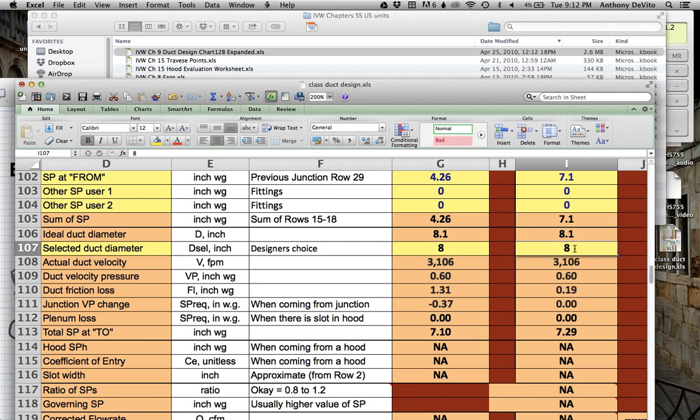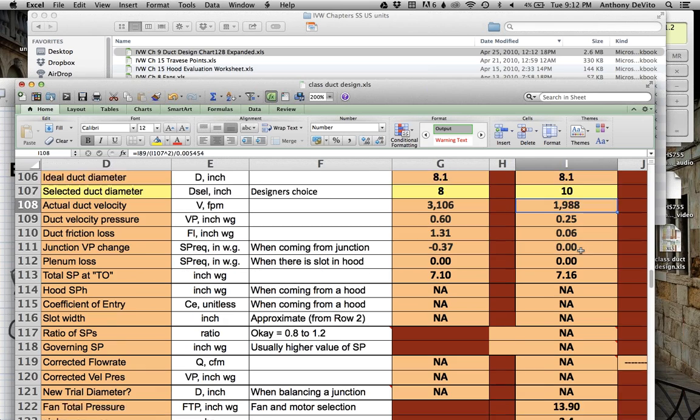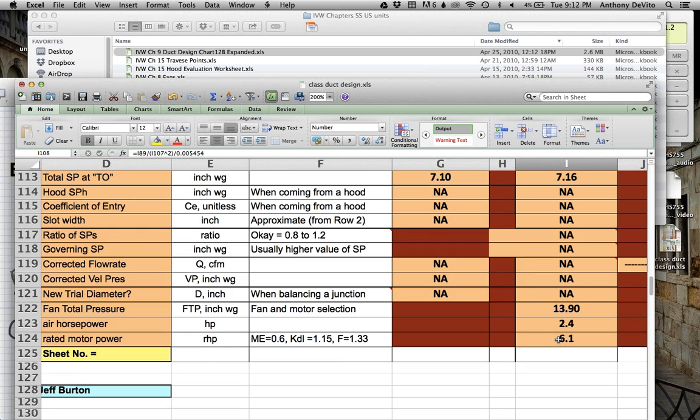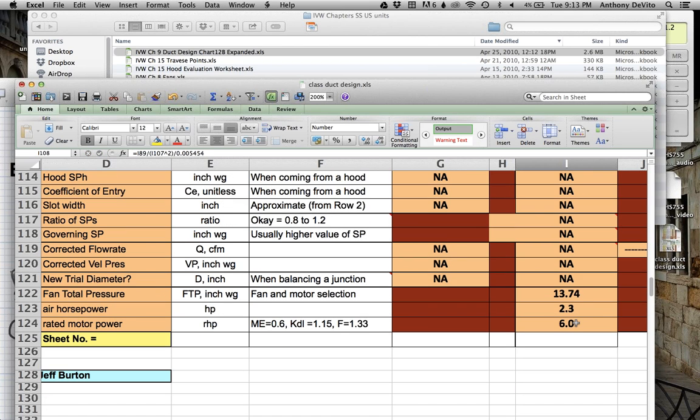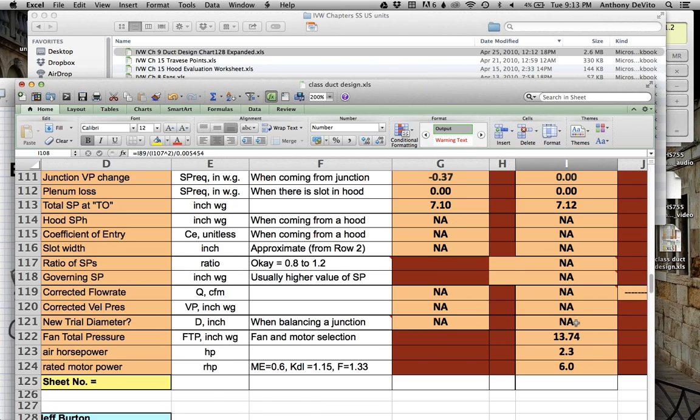Well, maybe if I made the stack duct 10 inches instead of 8 inches, I'm only going to get 2,000 feet per minute, but I'm already past the filter. What does that mean? That means I really don't have the particulate anymore. I can afford for the stack pressure to be lower because I don't have to transport those particles. So I'm going to make it a 10-inch duct stack instead of an 8-inch, and look how much smaller of, well, not that much more. Let's try 12-inch. Okay, how about 12-inch? Well, nah, it's not affecting it that much.